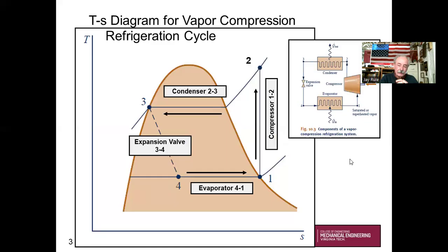You've gotten good at visualizing the process and the cycle on a TS diagram. You see the counterclockwise rotation. That immediately tells you that W dot net is definitely going to be a negative number. It takes power to transfer heat from cold to hot.